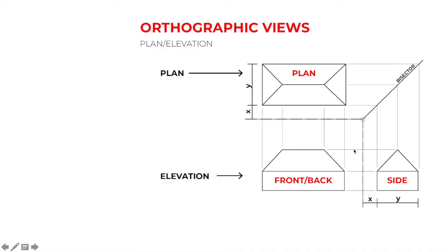The ability to draw the overhead view or plan view, side elevation, both front and back together on one page is interesting to us because it allows you to start at any one of these points. You could very well start to draw in one of the elevations, project these lines up to a bisector, and then start to form the plan. You see how the front or back elevation of this figure lines up perfectly, and how heights are matched from the side elevation to the front.